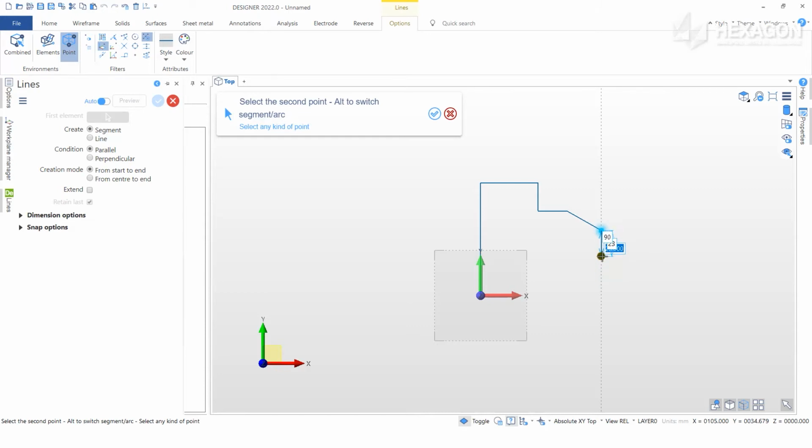By hovering over the datum work plane, you can wake up the X and Y axis. You can then move the cursor to the right and snap to the Y0. Position the cursor under the previous endpoint and it will snap to a vertical line. You can now enter coordinates for the endpoint, 0,25 in this example. Create another horizontal line 20 millimeters long.